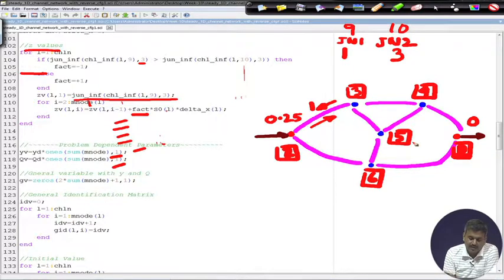Obviously, the natural one was 1 to 3, this will be 3 to 1. So, obviously this is at a lower elevation, this is at a higher elevation. So, I should start from 3 and I should increase the section elevations by S naught into delta x. Like that I can calculate the Z values for different sections for different reaches.